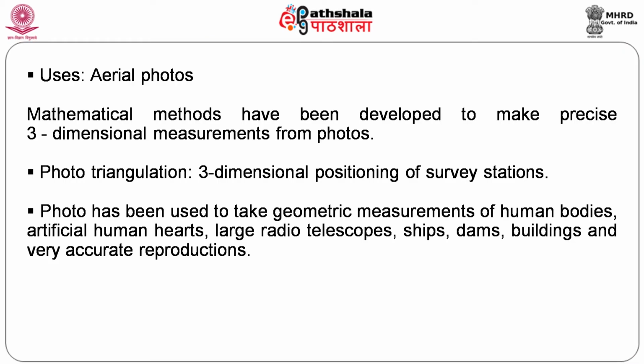When you are trying to use aerial photographs, especially in 3 dimensions, we are trying to make what are called measurements on the aerial photograph. What measurements are you going to do? If I am going to measure the distance from point to point and also the area of the object, I should get a 3-dimensional positioning of that particular station, for which we normally use what is called photo triangulation. So, normally we call it aerial triangulation or photo triangulation.